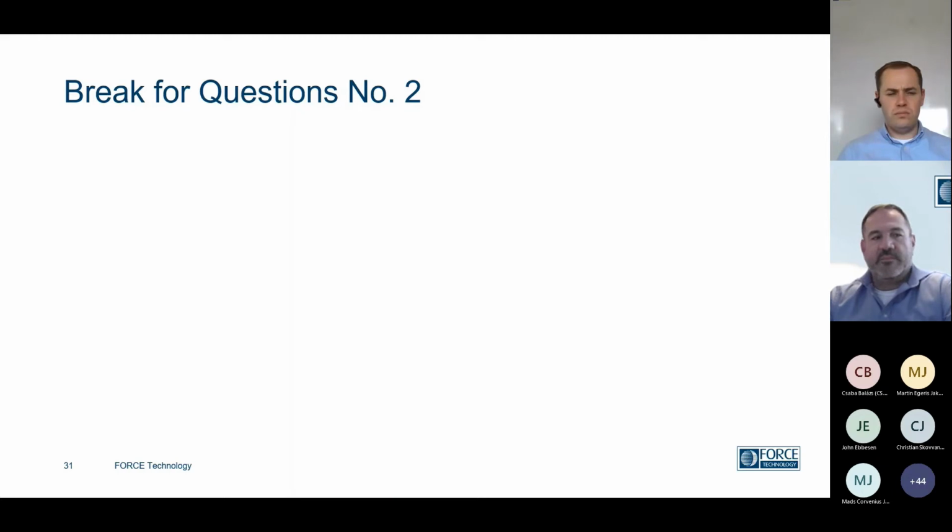Yes, you can. If you just use your, you can predict it, and then you don't have to do these curves. And I think maybe that's, if I'm turning the question around. Yes, you can do numeric methods. You can use finite element analysis, and you can guesstimate the fatigue life from there, and it can also be accepted. It all depends what the needs are and whether you want to accept the conservative results, but definitely.